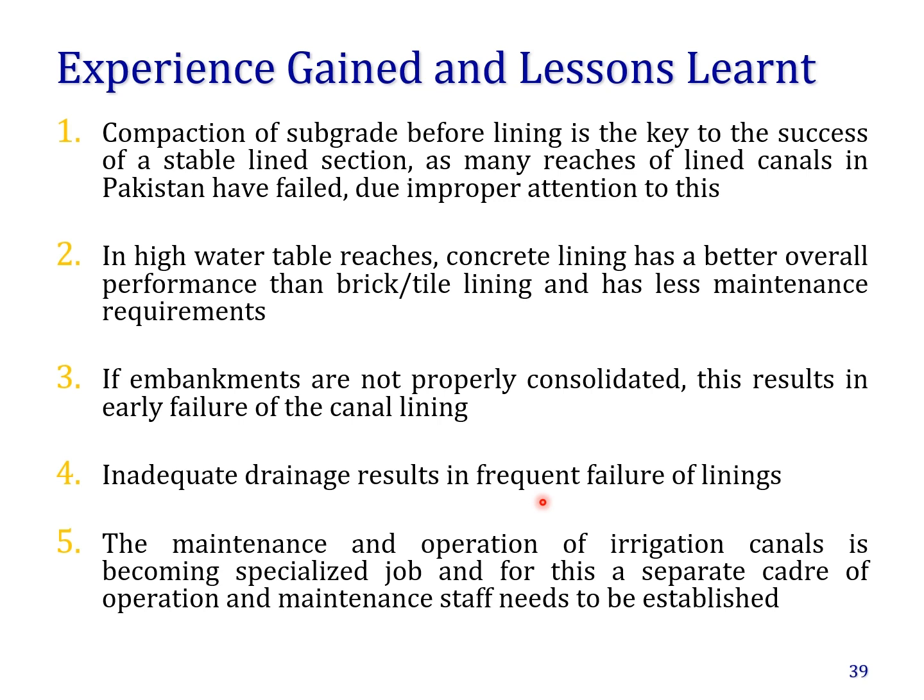Whatever lining you have, there will always be some seepage, and that seepage water beneath the lining can cause pressure on the lining, especially when the canal is empty. If you have a drainage system like the one I showed you for the Ghazi Barotha Canal power channel, where beneath the lining there was a filter material, then your lining will be long lasting.